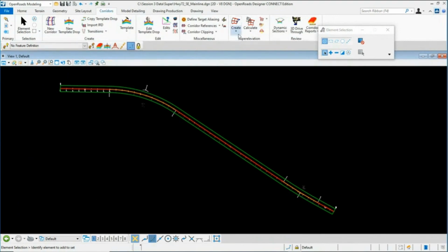So what I'm going to do here is we have a couple tools for creating the lanes. You can create the lanes manually, and generally the lanes are created with just horizontal offsets. But I'm going to streamline the process a little bit. I'm going to create the super elevations by utilizing a road template. Okay, so I'm going to navigate over here into my template library, and we can take a look at the templates that we're going to use on our divided highway project.